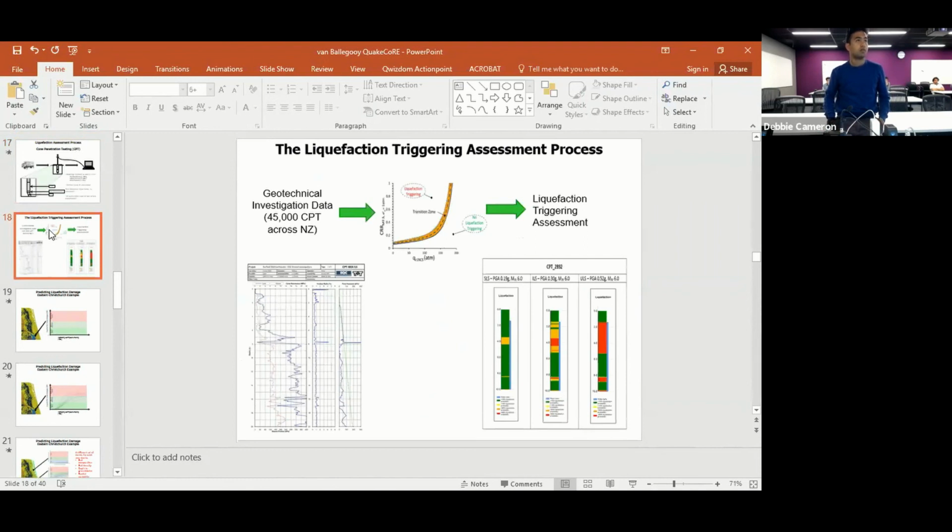In Wellington as well, and even in Blenheim, gravels also start coming into play. So when you look at the applicability and the performance of simplified procedures, what role do you think the soil grain composition plays in it? Surely that also has a large influence, more than just system response.